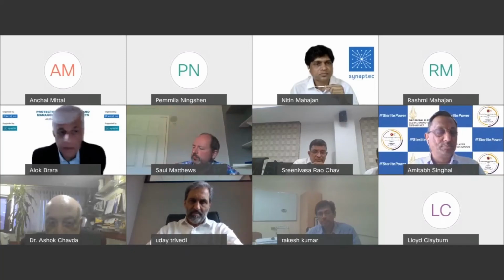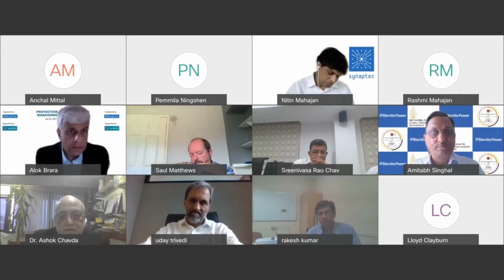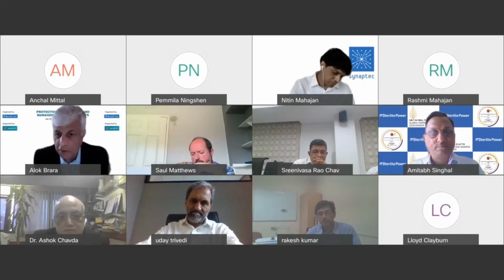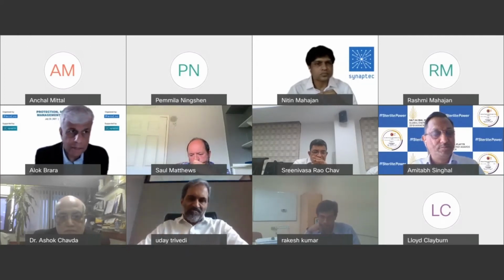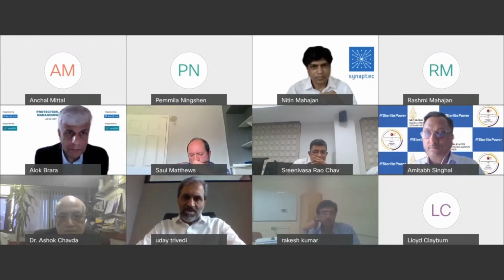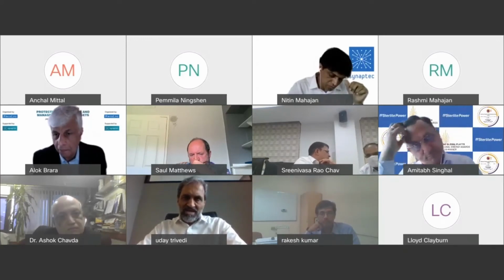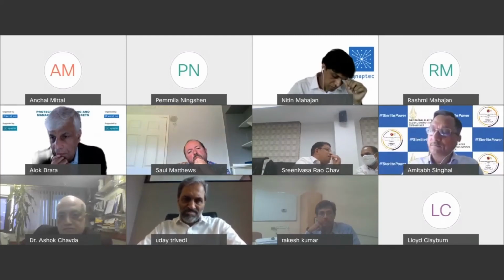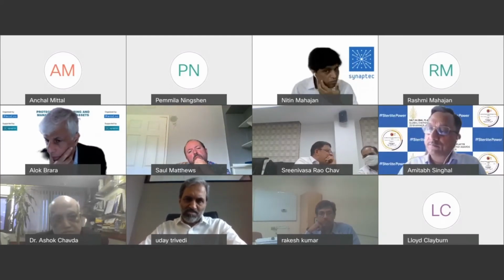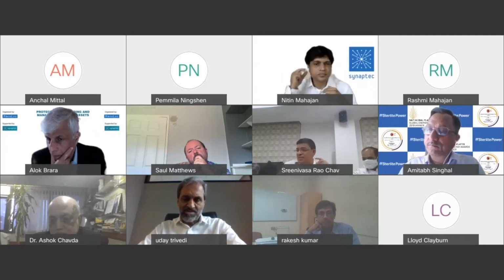Okay, great. If I can now go to the same question to Mr. Trivedi. Mr. Trivedi, what are the biggest concerns and issues you have right now? So one concern is earthing systems and lightning systems. The earthing system has taken a backseat. We hardly understand earthing. We only mean earthing is a pit. So the design of the earthing system is actually very critical. That is one concern as far as the technical aspect is concerned.